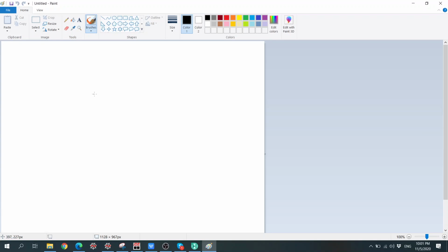So what we do basically, we have one unit, and then it goes here, and it goes to the other unit, right? And then this part, we want to send it back to this, which is your incoming, basically, right? So this is then our recycling. It has this kind of symbol in HYSYS as a recycle.